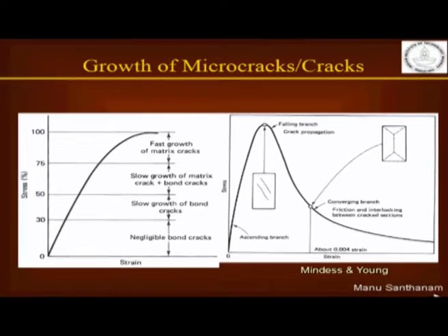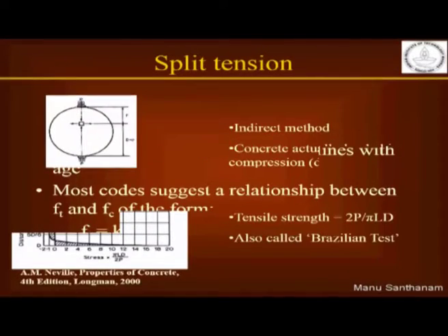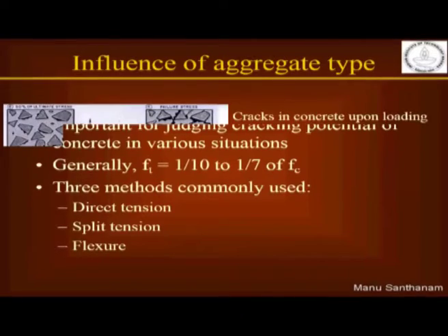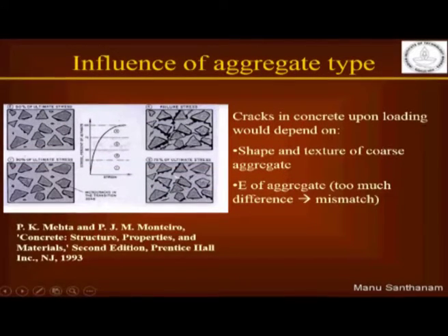Alright, so please recall the drawing that I had shown you earlier regarding how the concrete actually cracks. I will go back to that drawing in just 1 minute. So, that is the schematic suggested by most people as to how concrete actually cracks and how the cracks grow into causing failure. So, yeah, at very low load levels, you have cracks around the interface.